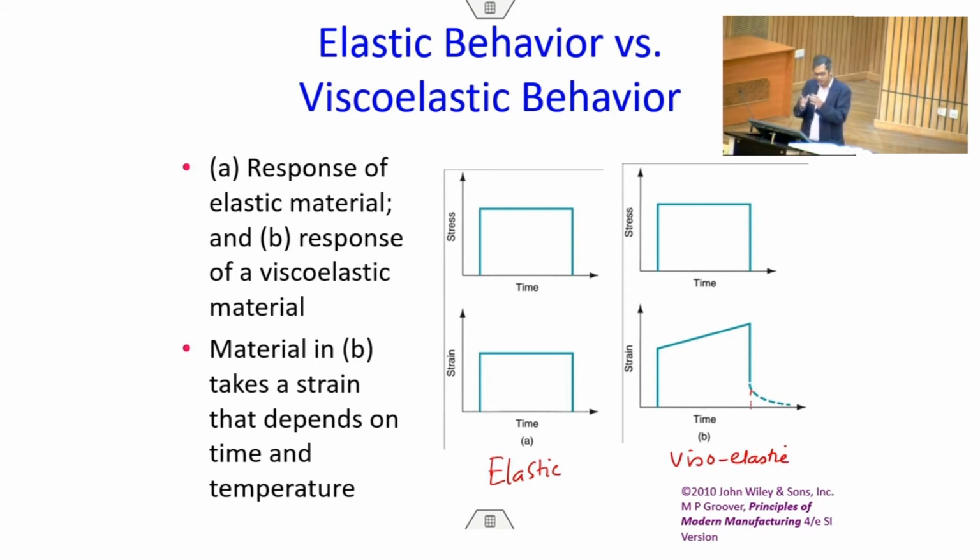Although it is elastic behavior, and the shape should come back to the original position, it takes time. In the case of elastic materials, it happens instantaneously. It does not take time, but in the case of viscoelastic, it takes some time to come back. That is mainly because of the viscous behavior of the liquid. Although you have applied the load and the molecules have extended, they are stretched basically. So, coming back to the unstretched condition takes some time.